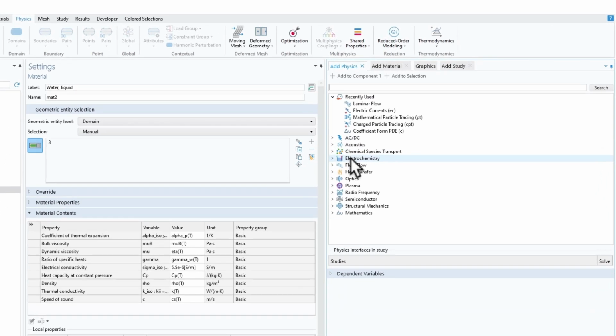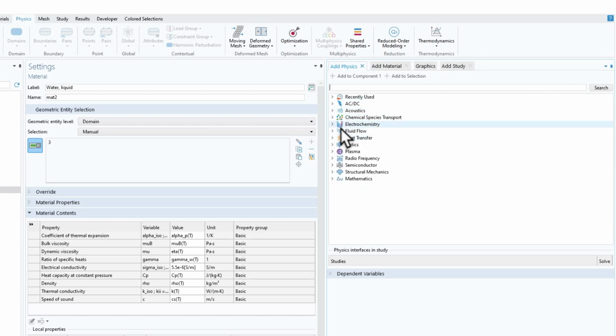And so here, let me explain what we are going to select. For this simulation, I'm selecting the physics interface under the multiphase flow category, specifically choosing the option of two-phase flow level set and then adding the laminar flow.